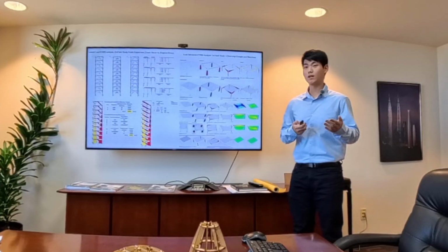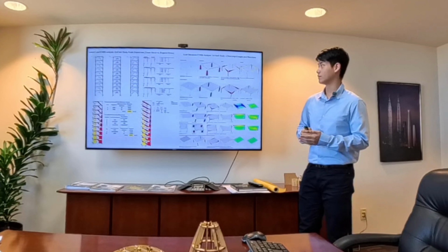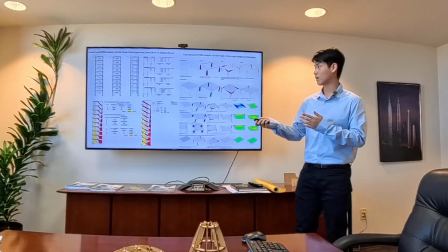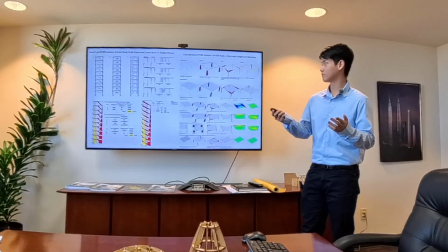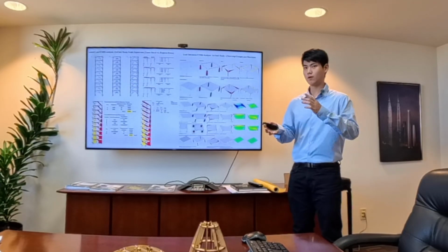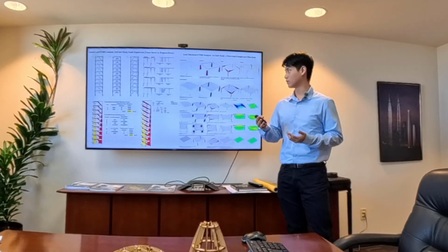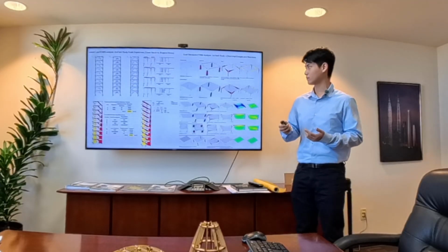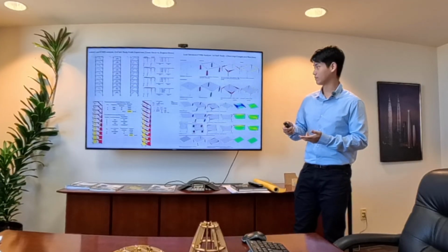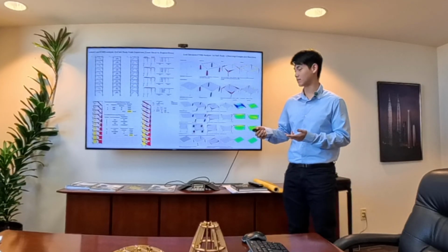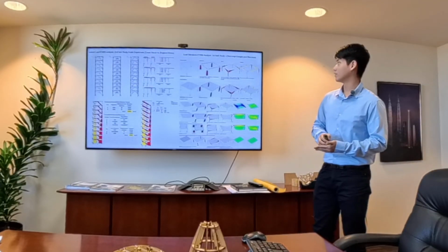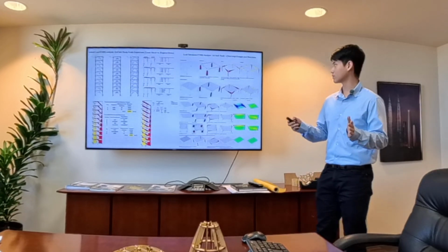In my second self-study, I studied lateral loads and the effects of lateral connections. So the effect of cross-bracing, lateral bracing, and V-bracing, and how each individually influences the overall reactions between the towers, seeing how the differences can be pretty noticeable, as well as calculating the moments and axial forces and comparing with ETABS.